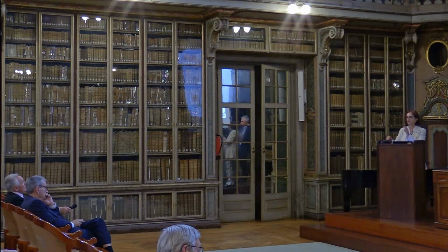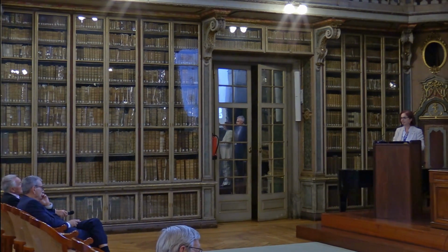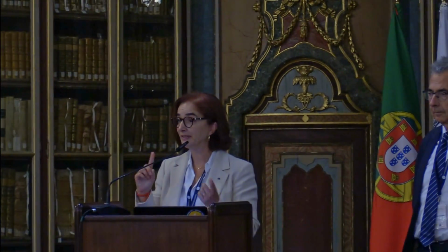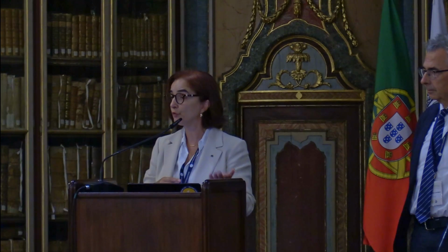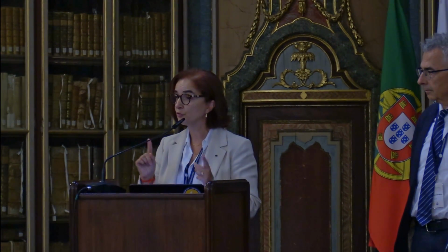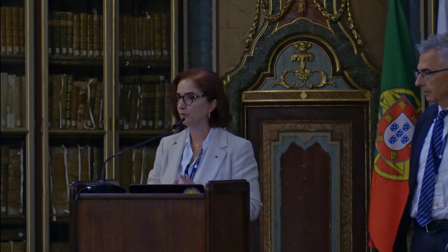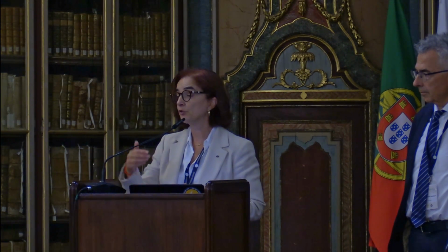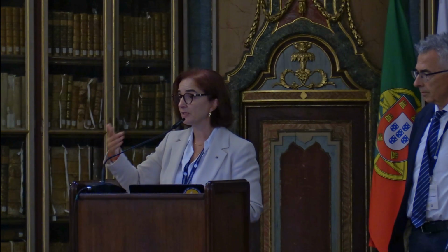Yes, it is possible, and it also depends on all the deposition conditions that we are using, and on the types of lasers. If it is infrared or ultraviolet, it is possible to change the properties of the graphene layer that we are producing. Nevertheless, for this case, we are targeting high conducting graphene, because this is what we are looking for. But also, for example, for synthesizing other materials like zinc oxide and other metal oxides, it is possible to adjust the electrical properties.